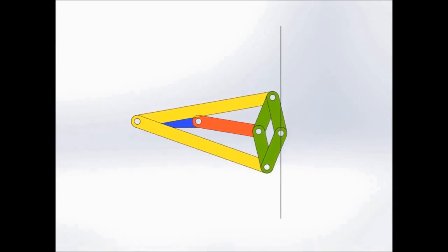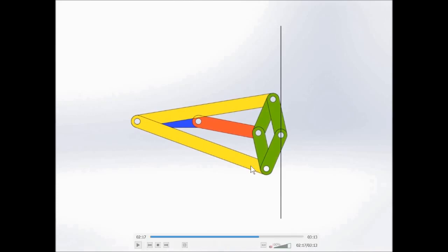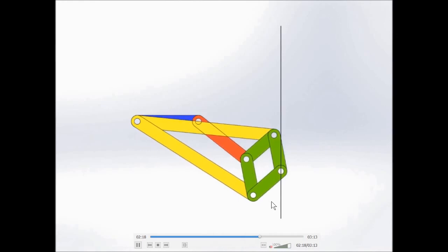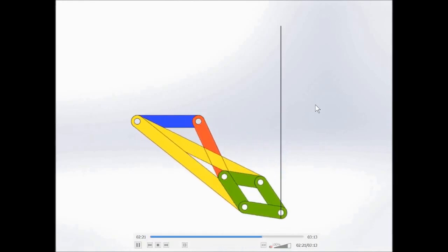Now we move to the exact straight line mechanisms. The other three are approximate straight line mechanisms. Now we have exact straight line mechanisms. So here we have what is called the Peaucellier mechanism, which is again in your syllabus. With this mechanism you will not get an approximate one. We will get the exact straight line, and no other curves will be obtained.